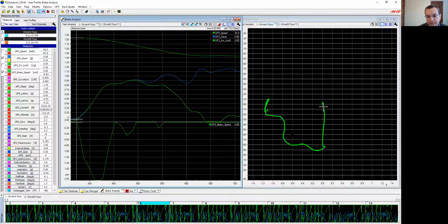The curve looks a little bit better in terms of what we're using for the friction circle, the transition from braking to turning, but it's kind of late in the event. So probably there was still some compression here that could be done, even though we don't see a dip after the peak braking point like we did here back on lap 4.